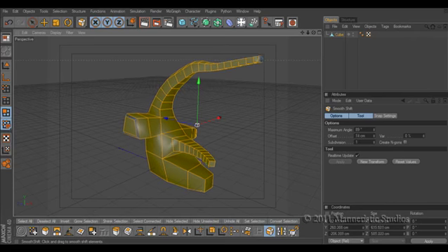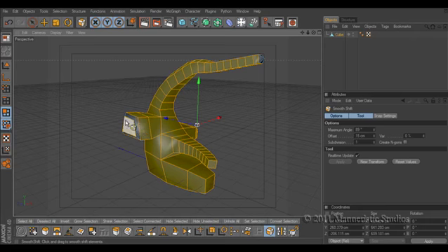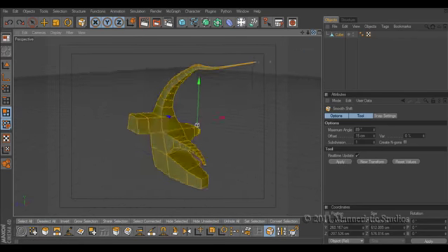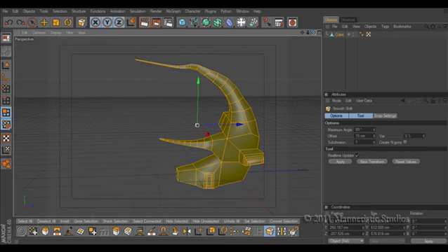So you see this one face here that's jetted out is starting to make a more rounded area. Okay, good for certain areas of characters, vehicles, or props. It's not something you want to do too much because you're adding more faces. The trick to polygon modeling is to work with the faces that you need. If you start out with too many faces, you'll start out with a lot of problems. It's best to start with as few faces as possible and add on to what you actually need to create the model of your choice.